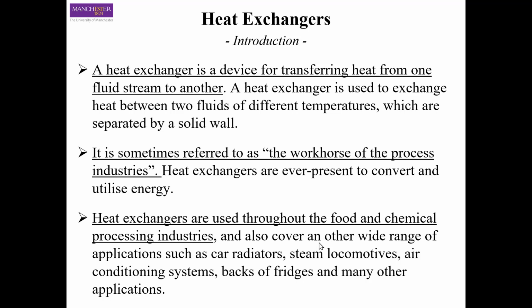One process fluid can be, let's say, steam, and you are heating another process stream, like for reactor heating, or you can use refrigerant as a cooling agent to cool down some process stream. And normally this heat transfer happens across a solid surface, or a solid wall.